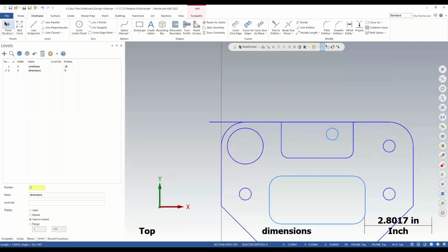And you can also use it for points. So if I have like a point in here, I could double click on that point, and really you can only change the position, either move it or copy it. There's not really any other things you can do with a point, just by the nature of it being a point, but I can grab it, move it somewhere. And again, if I grab it, I can hold the shift click on the point itself. So if I know that this has to be like 2 inches to the left, I can grab the axis of this, move it 3 inches to left, enter, and there it is. And then when I'm done with surface level editing, as the command prompt says, I can hit the escape key, and that gets me out of the function.